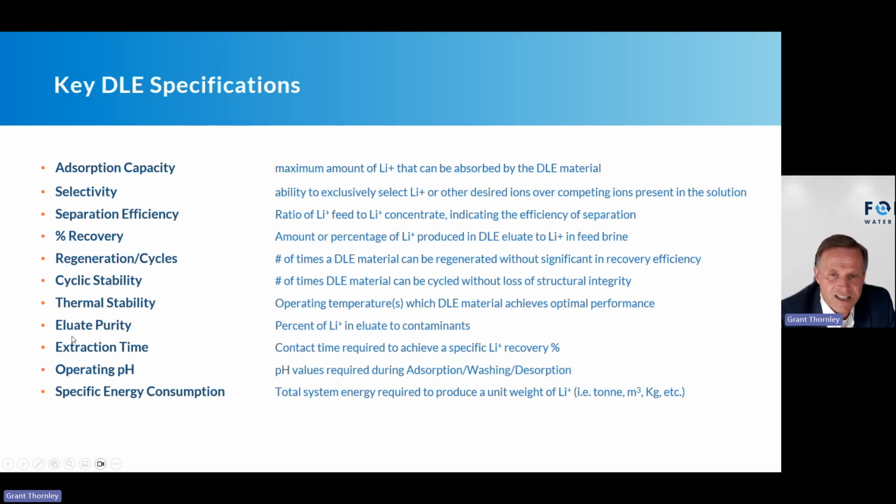When you're doing your testing, you want to grab a lot of samples of the eluate quality coming off. Typically, when you're doing your initial testing, like every bed volume, you don't have to analyze every single sample you grab, but it's good to have that so if you need to go back later, you can take a look at that grab sample. So eluate purity, we really want to focus in on that.